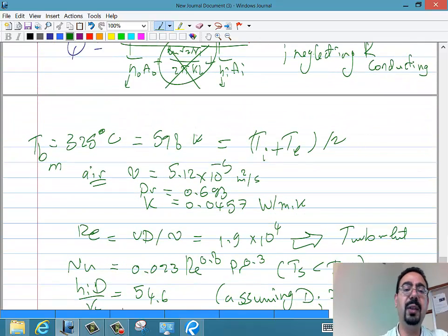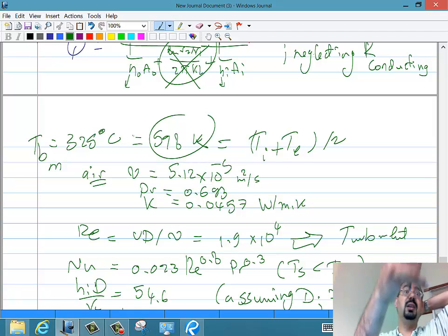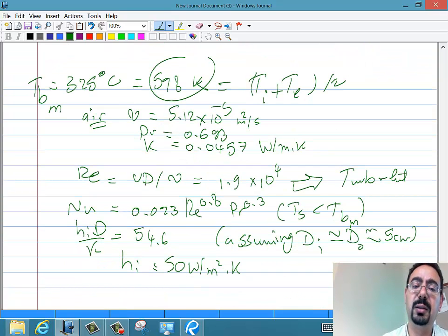No, that Kelvin is actually just for the table. So I guess the table that I used had Kelvin in it. If the table is reading degree centigrade, go for it. If the table is saying Kelvin, is it degree C? All right. I guess the table that this problem came from, this problem was from another textbook, and they used a table that has K in it. Also, if you check the table and you come up with different nu and Prandtl number, don't panic. Sometimes the properties are not exactly the same from different textbooks. That's okay. You will be judged against this textbook in the exam.